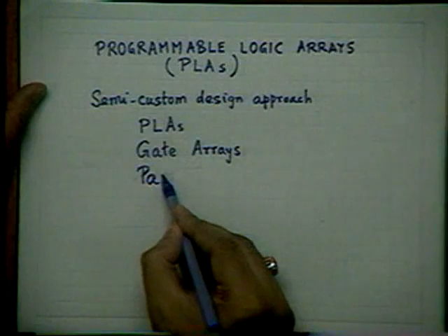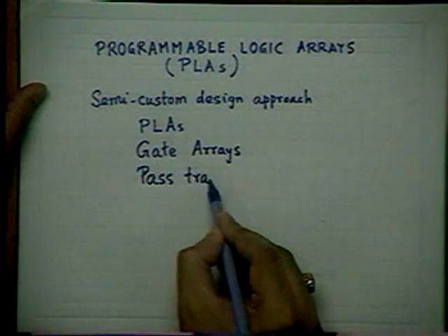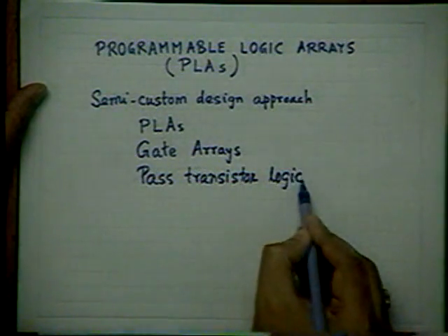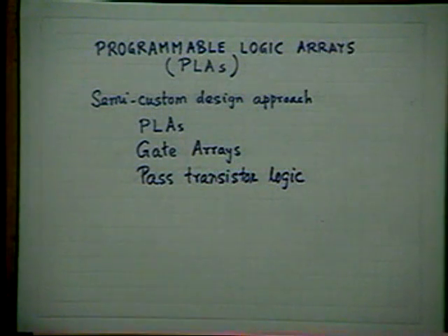On the other hand, you have got some indication of such a thing in pass transistor logic, which is of course not that popular today. Let us consider the pass transistor logic case. You remember the pass transistor logic can be so configured that it is an array of transistors. Only thing is you have to program it suitably. Already transistors are there on the chip. You have to connect the transistors at certain nodes only using some mask at the end stages, not in the beginning stages.